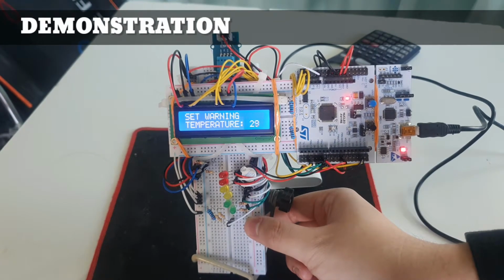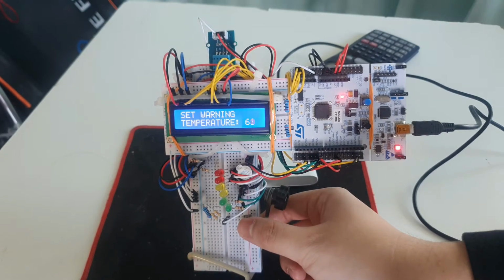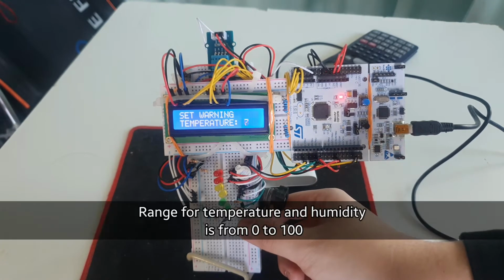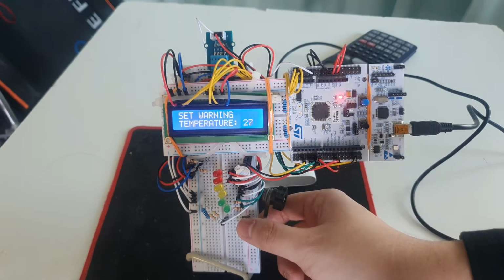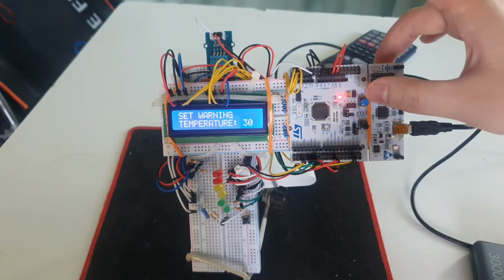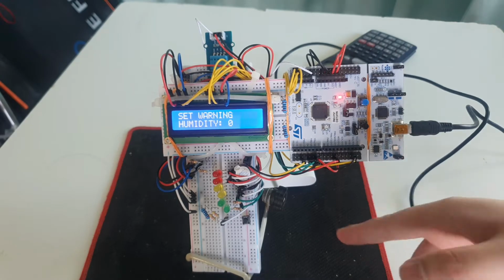Now, assuming you want to set it to 30 but it has already passed, right? Don't worry, it will return back to 0 and give you another chance. It will go from 0 to 100 and it will increment again. So let's say we want to set it to 30 degrees Celsius as a warning, and then we press the blue button to go to the next setting, which is the humidity setting.